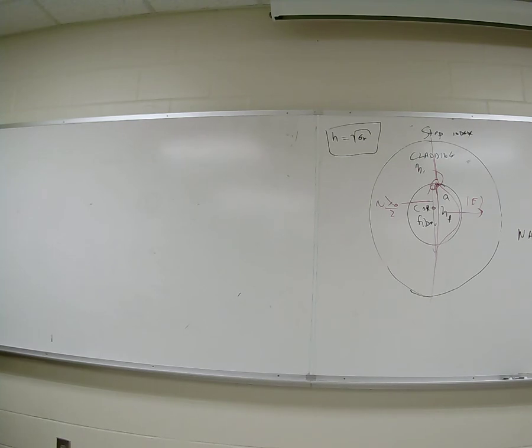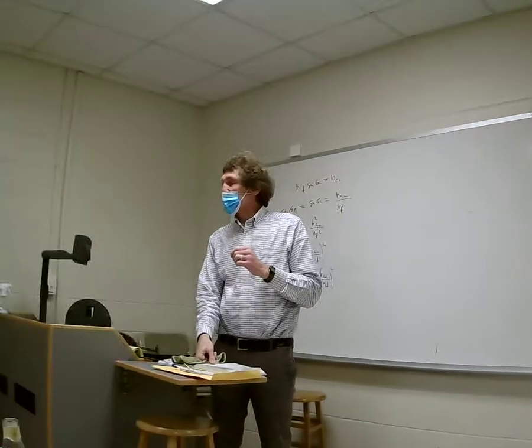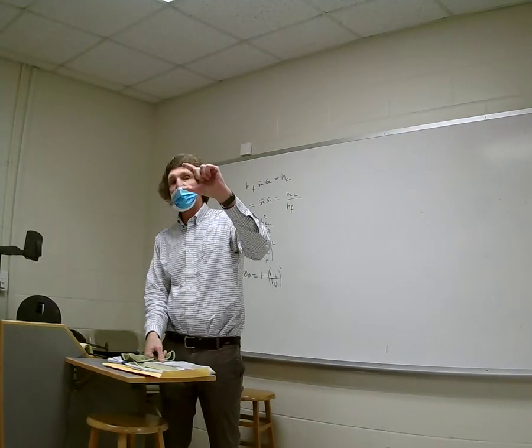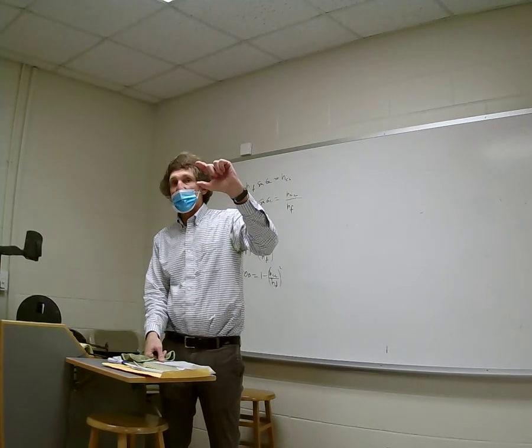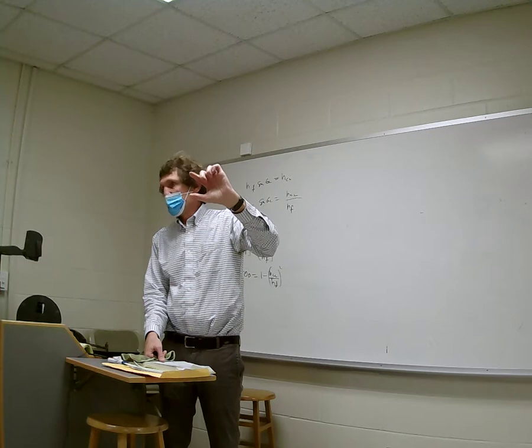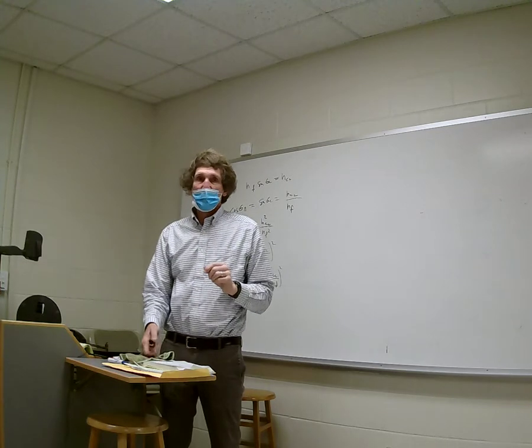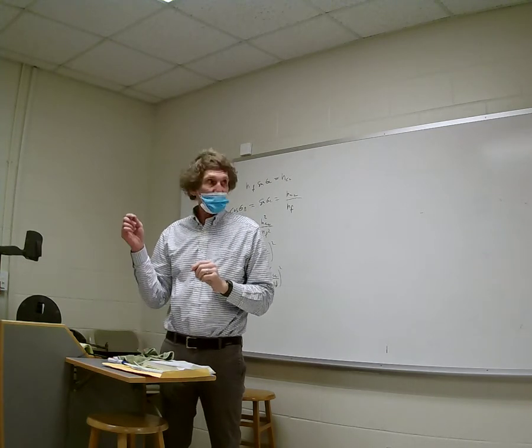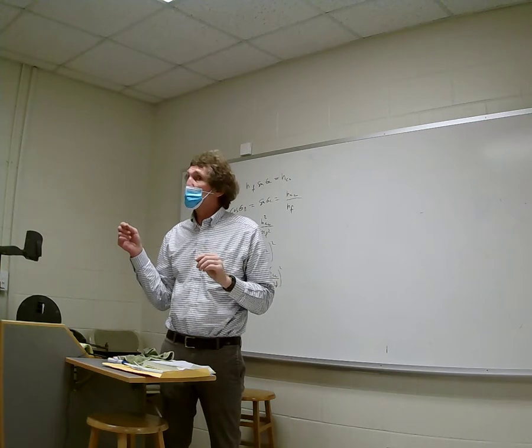I don't worry about dielectric waveguides too much. They're just a couple of mirrors. That's all a dielectric waveguide is. It's a couple mirrored surfaces stacked, and you just figure out the cutoff frequency for a single mode is you get a half wavelength between them, just like a rectangle. That's it. And Whitworth's book's got a lot of information about the modes and stuff. You don't need to worry about it. That's my opinion. Okay, now, are there any questions before I move on to antennas?